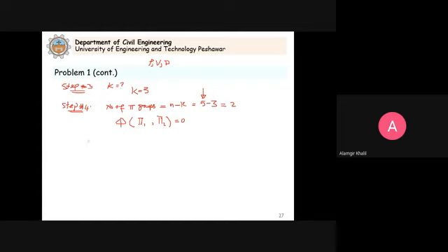Step number 5 is the important step, the tricky and difficult step. Now we have 5 variables and we need to make 2 pi groups. So it means that k number of variables you need to select as repeating variables, because we are applying the method of repeating variables. So in the 2 groups, 3 will be repeating in both.